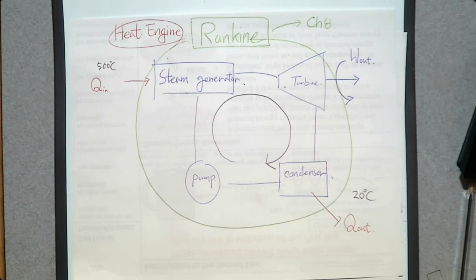In a normal steady state operation, we assume that the amount of water in the river is plenty enough. So even though we continuously produce electricity, the inlet of the coolant system is going to be at 20 degrees Celsius. But what if the river is dried out? Then the temperature of the river is going to increase, and the temperature of the condenser is going to increase from 20, 30, 40, 50, and eventually the power plant stops, right?